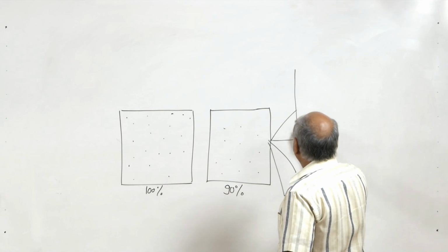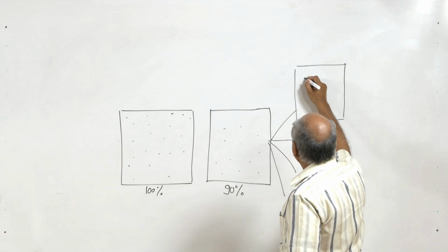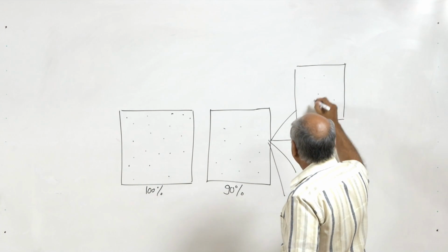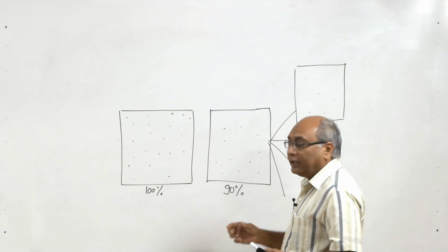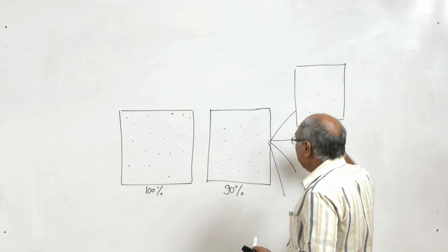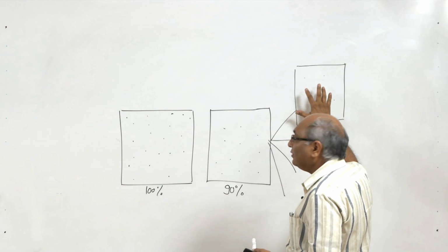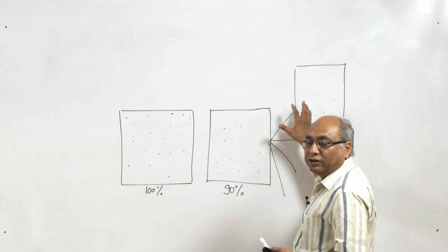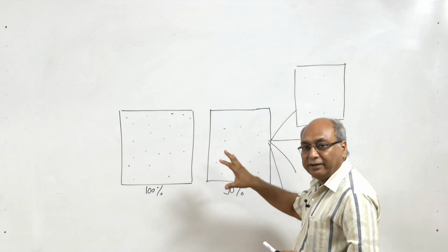So for example, I am having one DEM which has been generated. Now those 10% points I will use as test points or control points, compare the corresponding cell values, and whichever will give the closest values, I will consider that that is the best digital elevation model, that is suitable for my input data set.